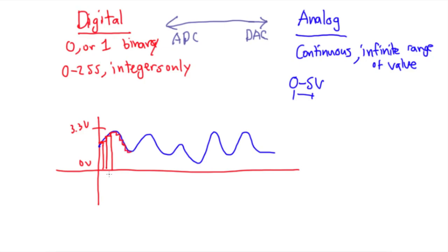So the time between these is the time it takes to convert the voltages in this signal, and so it's effectively going to look a lot more like this. The way you can make this a lot better is to speed up the time it takes to convert the voltages. And again, with the idea of bit depth, it can only be a set amount. It can only be set voltages.